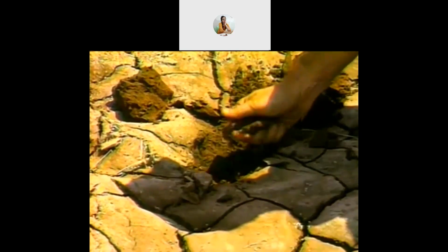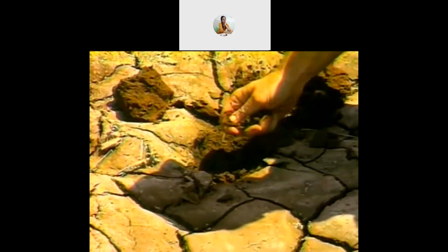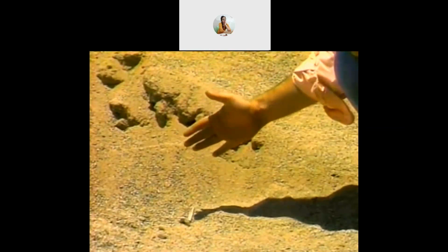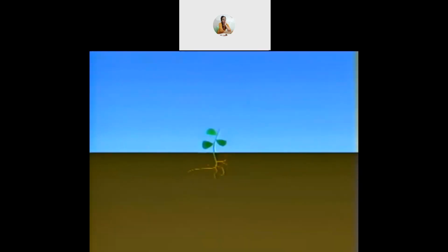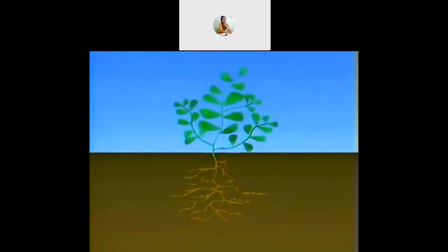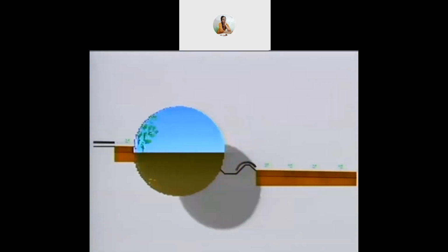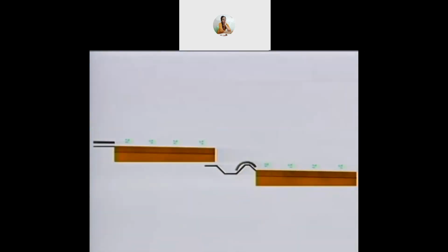Number 2 is surface irrigation. Its advantages are, firstly, low cost of deployment, energy, and maintenance. Second, it favors the increase of photosynthesis in the lower leaves due to the reflection of the light in the water. Third, the wind does not limit the irrigation. Fourth, it promotes the fixation of atmospheric nitrogen as a result of favoring the growth of blue-green algae.